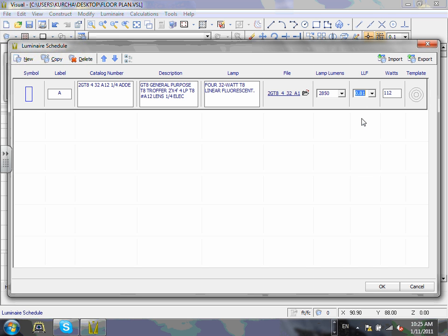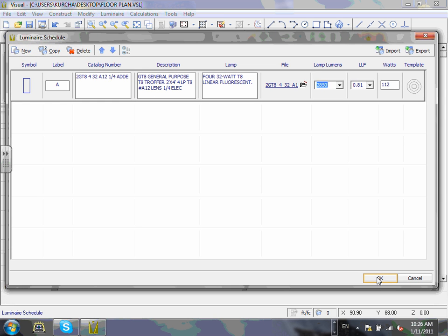That's the only thing you need to do for this fixture. Here's the watts of your fixture. Later on, it comes with these lumens, standard lumens. You can change these lumens later on if it doesn't get you the right results. Stay with the defaulted ones, guys. Later on, you can reduce the lumens or increase the lumens. So basically, that's it. If you need another lamp, with 2 lamps, you have to load it with the 2 lamp. Okay, when we're done with this, just hit OK.